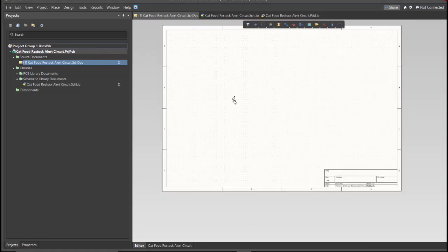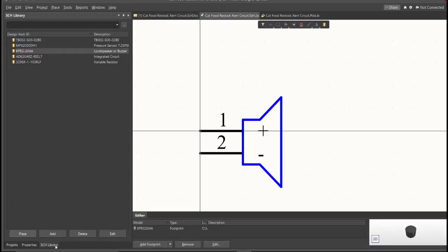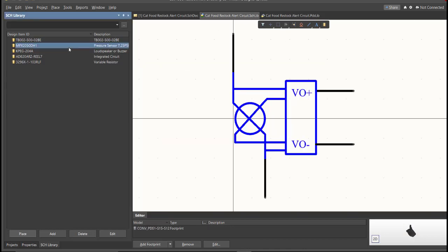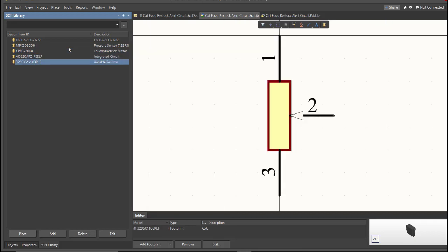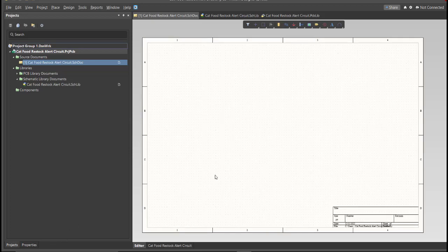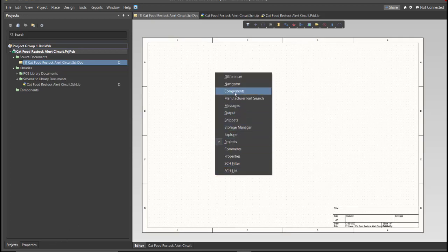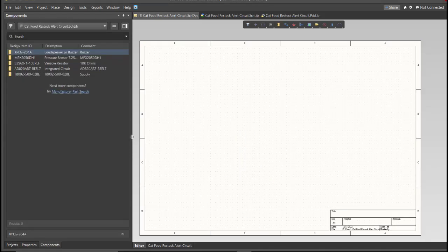After you finish all the components in the BOM list using a library loader, you can check here in schematic library panel all the added libraries. So, these are the added libraries for this PCB. Next, we're going to put all of this in our schematic doc. So go back to the schematic doc and click on Components. If there is no component in your panel, just press K on your keyboard, then click on Components. Now you can see here the library for this project. So we're just gonna drag the library inside the schematic sheet.